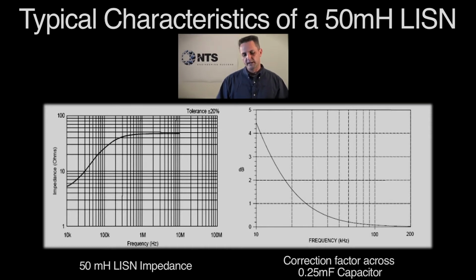The curve to the right actually shows the correction factor for the measurement capacitor, which is built into the LISN. This measurement capacitor is used to perform the voltage measurements, conducted voltage measurements for CE102, which we'll get to in following test modules or qualification modules.